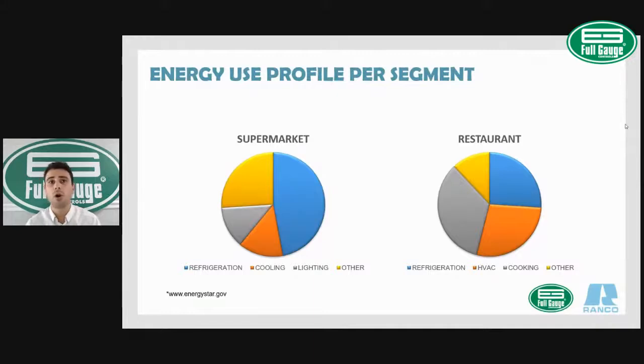And not only because of the resistance that is activated to defrost the ice, but also during the ice formation process, in which the evaporator coil loses efficiency. So there you have energy wasting, because your coil is forming ice, and that ice is preventing heat transfer.